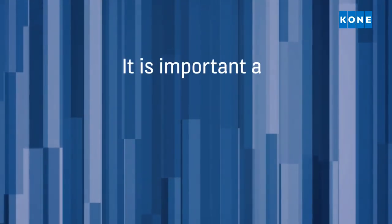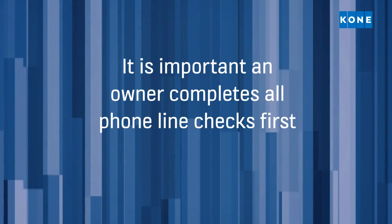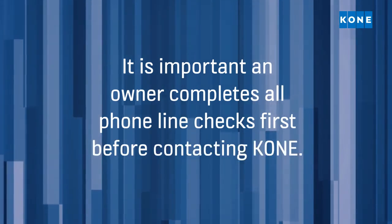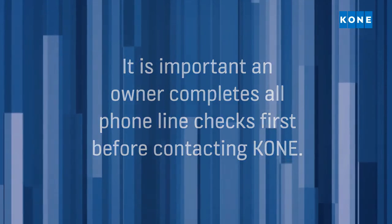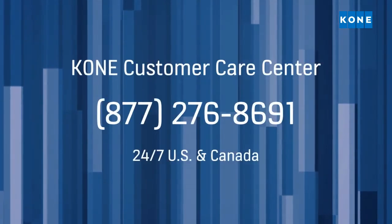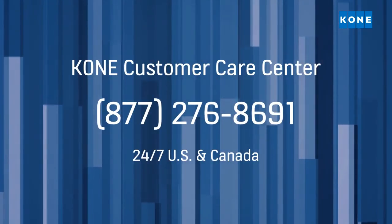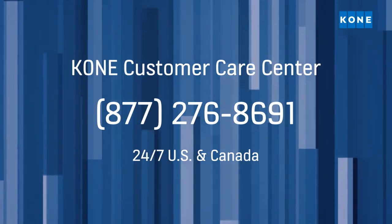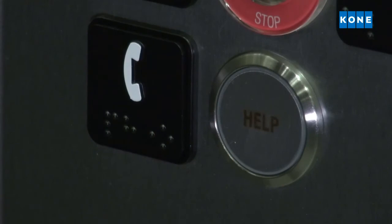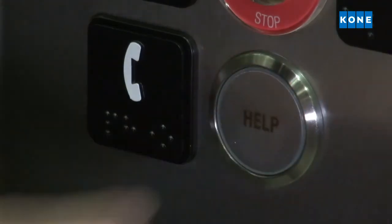It is important an owner completes all phone line checks first before contacting KONE. Once all phone lines have been checked and are active, if the elevator emergency phones are still not active, you should contact the KONE Customer Care Center and place a service request. Please note that by code, an owner should verify that their elevator emergency phone is functioning correctly on a monthly basis. Simply press the elevator emergency phone button.